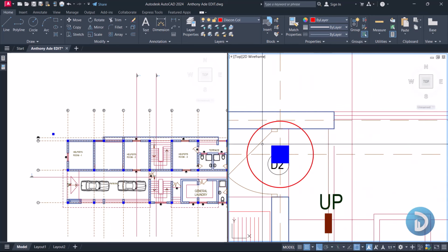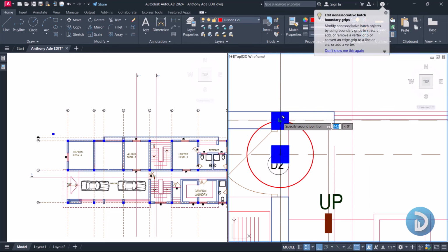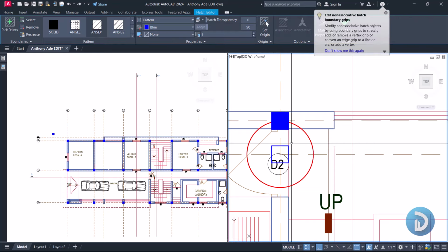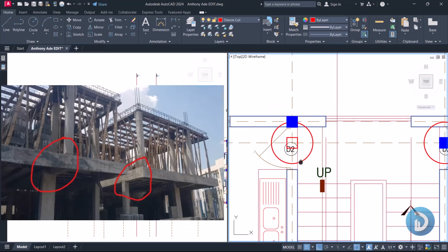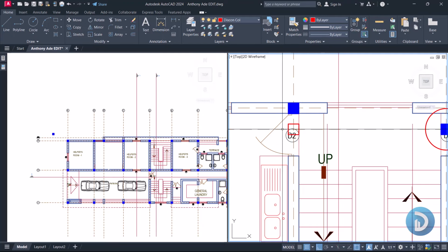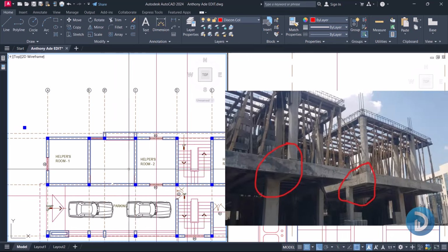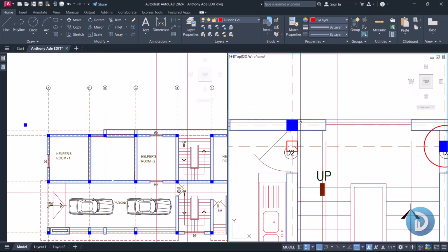So on this first floor, what we'll do is we'll create this copy and we'll put it at this center. Okay, then let's take out this hatch and we'll match, let's take out the hatch on this other column. Then we can match our discontinuous with this. So this is to tell us that when we get to this first floor, this column here will turn to a discontinuous column, which is in red. Then the column that we start at this very part is this blue column, which will be resting on this cantilever that we've taken from this other grid line 2 up to this point. Okay, so we've solved this very issue.